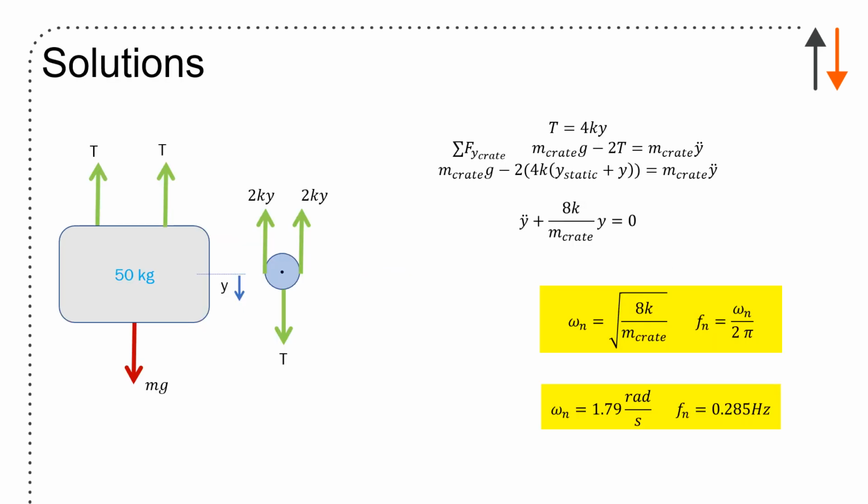First thing you do, you calculate your force, the tension. Tension is acting downward, and it's on each spring. Now, often this was a problem. Why did you make it 2ky? Because this cord, as it goes around, is inextensible, and it's attached, so it's a fixed length. So the only way you're going to get extra length is by stretching the spring. And so the spring takes up all of the stretch, k times 2y. So tension is acting upward here.